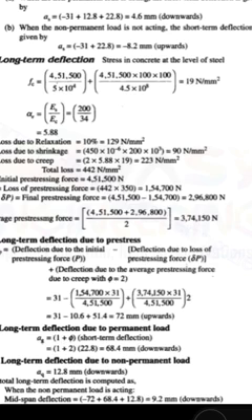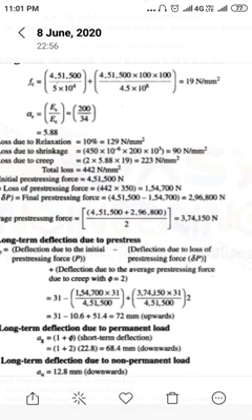So finally, 31 minus 1,54,700 into 31 divided by 4,51,500 plus 3,74,150 into 31 divided by 4,51,500, that has to be multiplied with the creep value of 2. Okay, so finally the upward deflection is 72 mm, you will get.